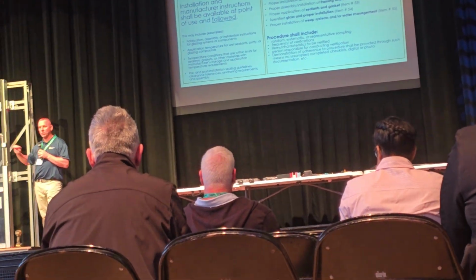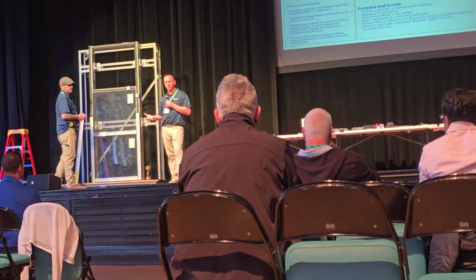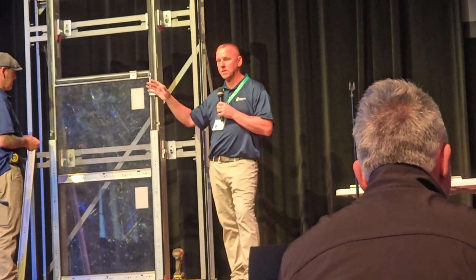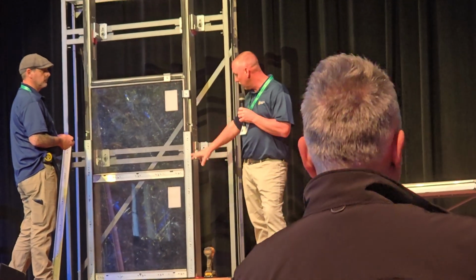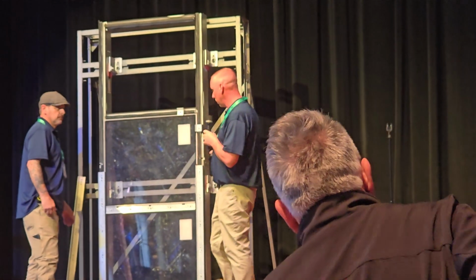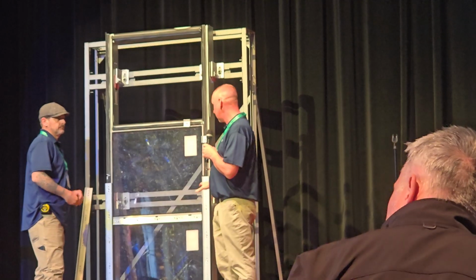Out in the field, when you get to this point right here, that's a good point, Scott. If you have a crew on one side of the building and a crew on the other side of the building, it's based on trust. It's based on a certified installer putting that curtain on that side the same as the other side of the building. And when you get to this point, the glass is all in, everything's buttoned up, you put your pressure plates on, all the screws are torqued to what the manufacturer says.